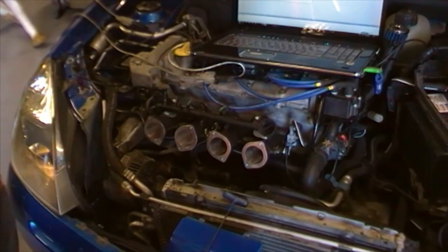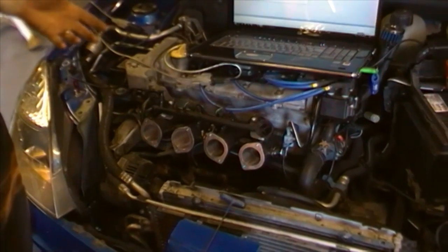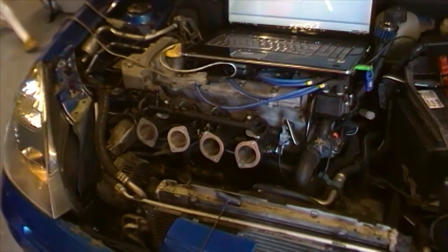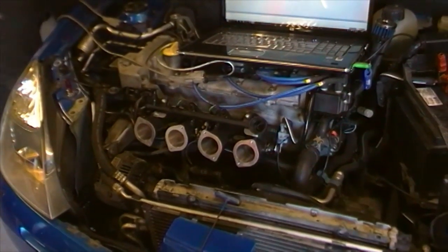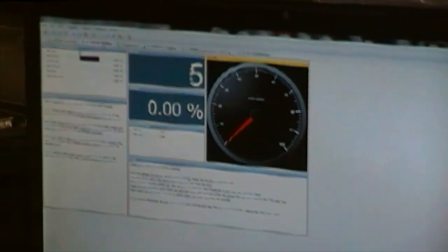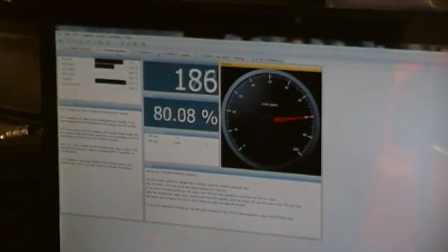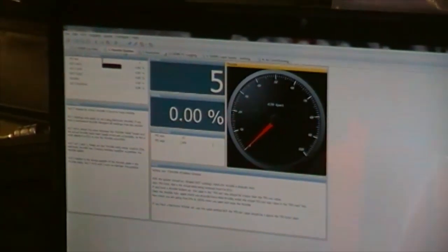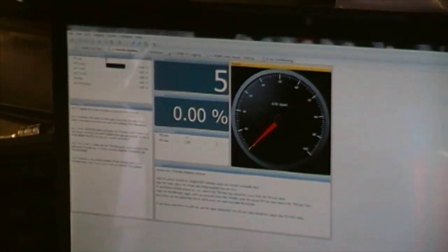Next thing to check is then in fact the TPS is where we need it to be. Obviously, having made some adjustments initially, we may have to make them again. So we now pop the ignition back on, and you can see that the TPS raw value has in fact gone down to 5, which is not where we left it. And maximum is 214, so they both have changed a little. So obviously now the balance is correct, we need to make that adjustment.